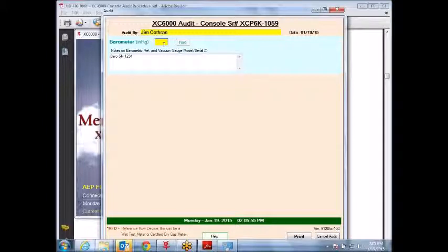So wasn't there a barometer in the Cal kit? There is, and you can use that. You've got to set it up. You've got to be a little careful with it. If you get it off of barometer mode and change it to like altitude mode, then climb the stack, it doesn't know the difference of pressure change from altitude versus barometer. If that makes sense.